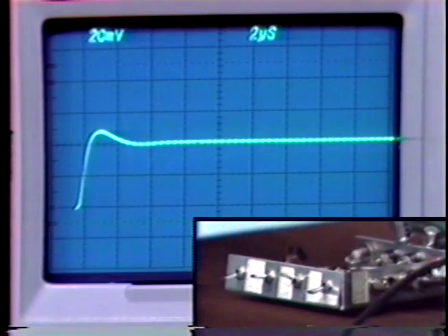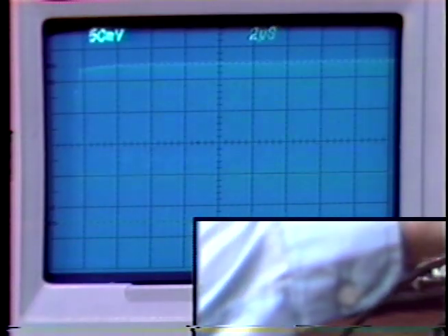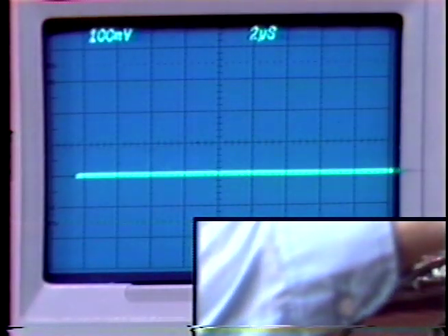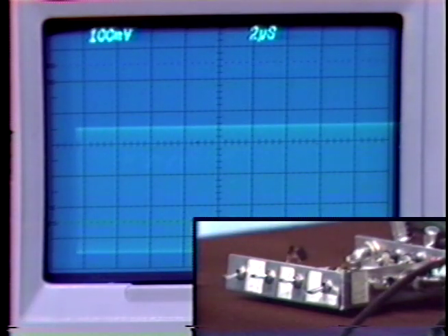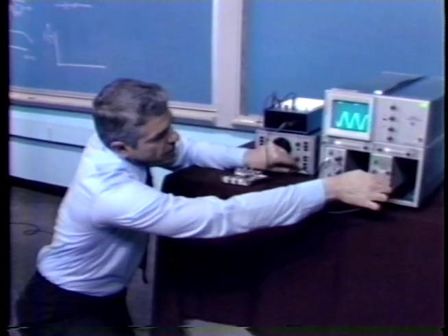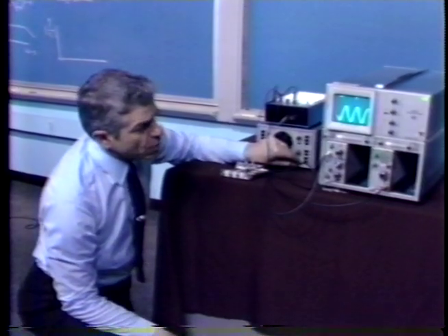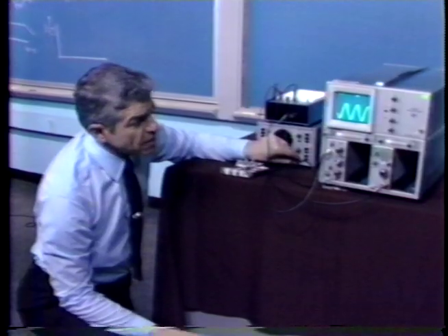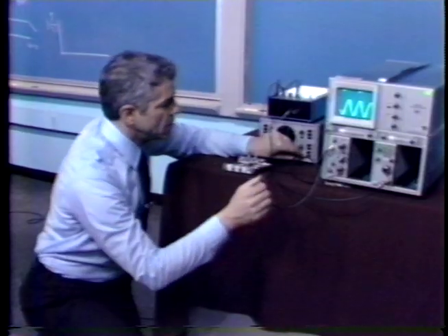We can see that. Let me go back to zero capacitive load. And we notice even if we eliminate the input, the amplifier is oscillating. Here the amplifier is oscillating at quite a high frequency, several megahertz, reflecting the fact that we've taken away the capacitive load, which is really necessary for stabilization when we use this sort of compensation.